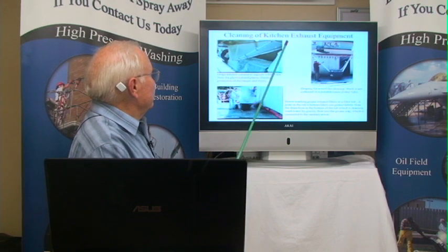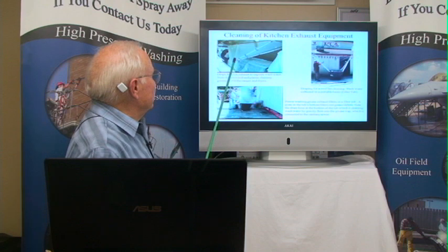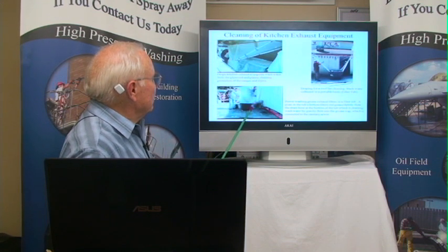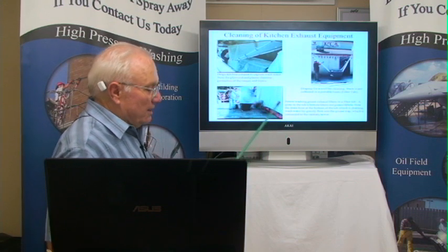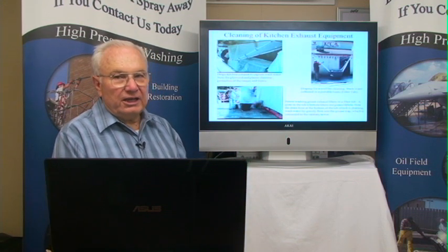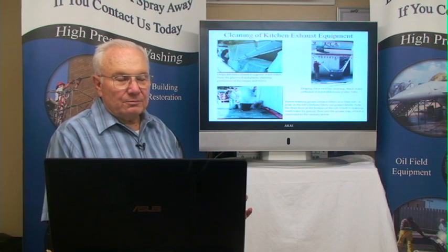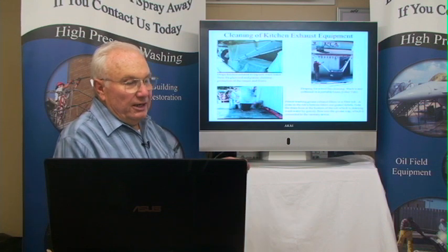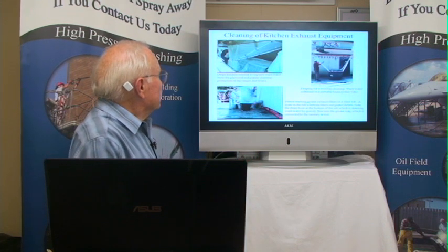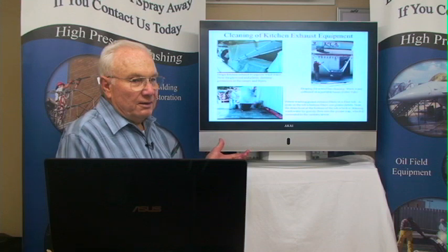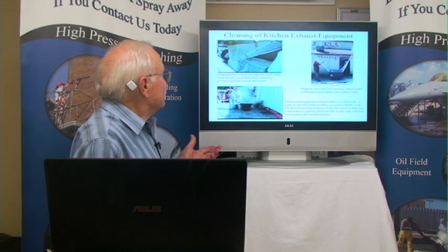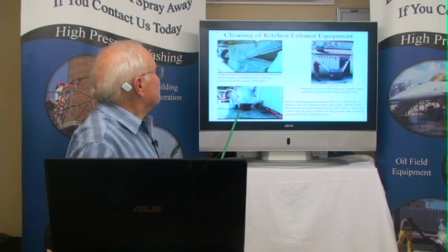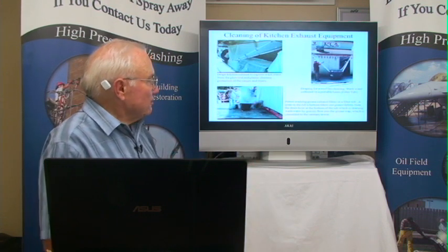Here's on the inside, and this is typically, you got to drape the hood down into a 55-gallon drum, and then at the bottom of it, it's similar to this. You can run that over to the sand trap, and most drains in the kitchen go to the sand trap. And most drains out into the eating area, if there are any, go to the storm sewer. And the slop sink, mop sink, goes to the sand trap. Not sand trap, I mean to be saying grease trap for a restaurant. So this is typical in there.